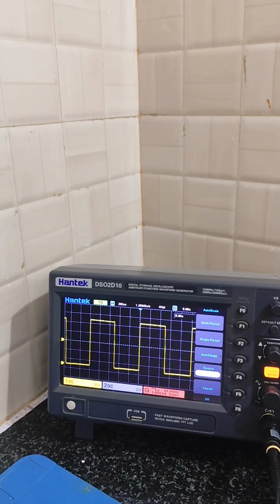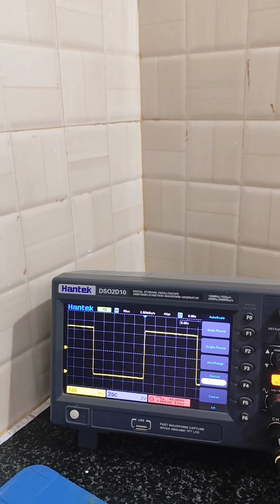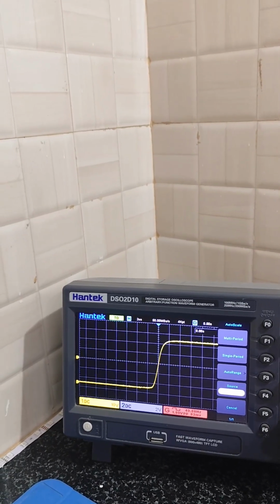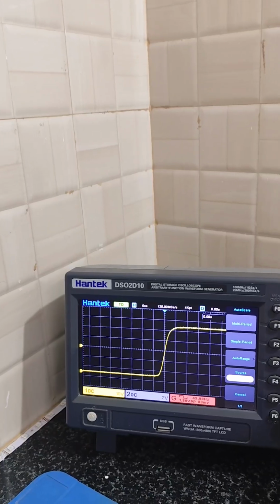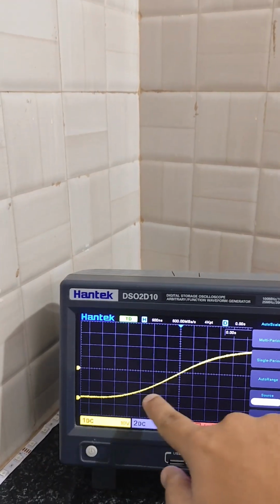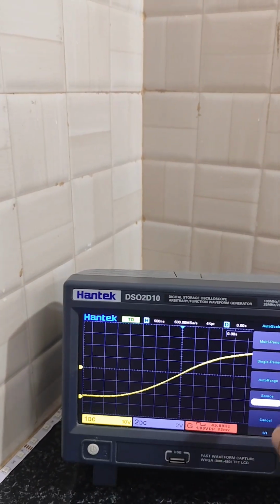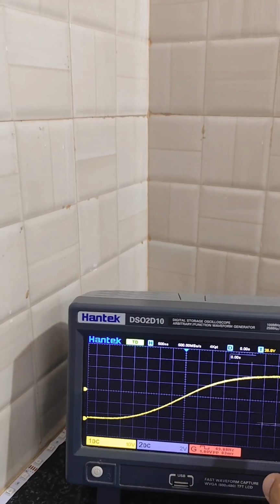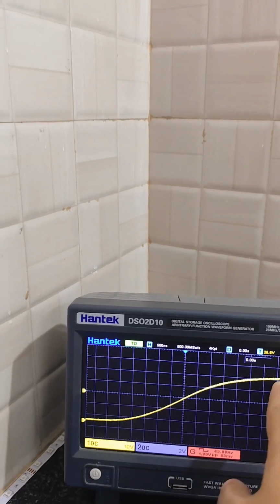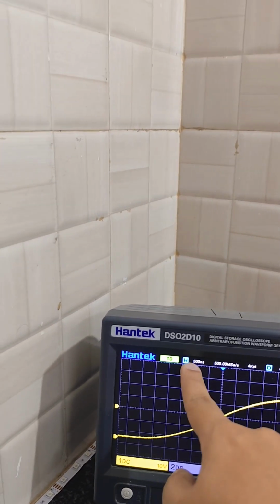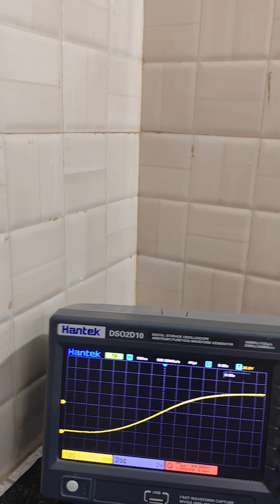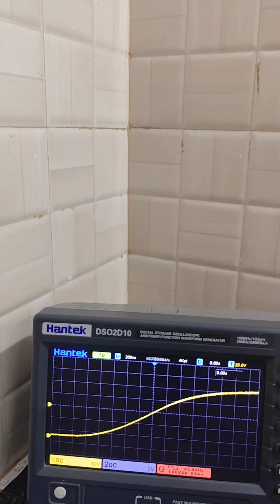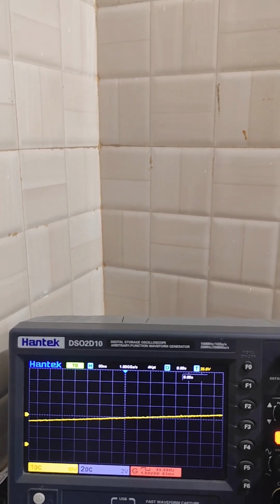So this is the time per division. If you change it, it changes the waveform shown. So you can literally see how the waveform is changing over time. Let me turn off. So in this time period, per division means 500 nanoseconds. So it's at 500 megasamples per second. And if we go to the absolute maximum, it's 1 gigasamples per second.